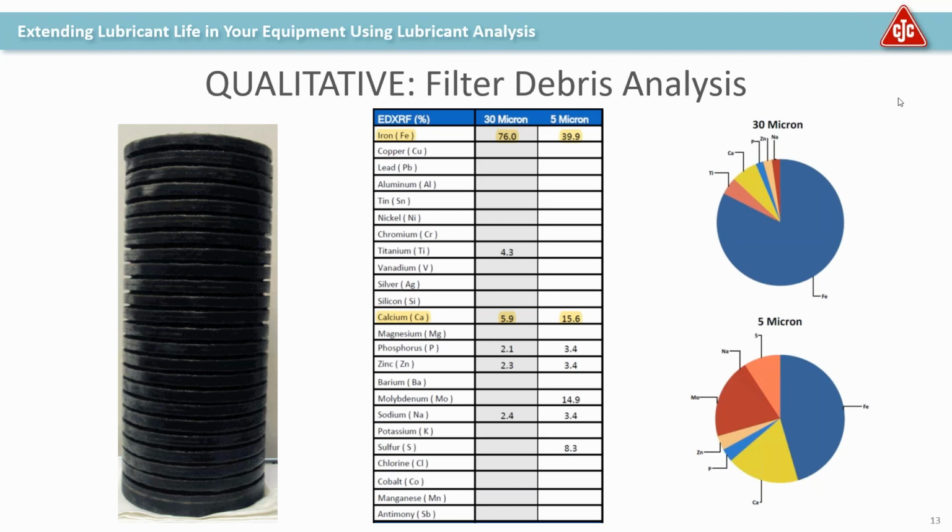So a couple thoughts I have on that is that I think it's dependent upon the application and the system. And anytime you go to re-additize the system, you have to be extremely careful. I know I've seen a number of horror stories where people have used basically splash. They just throw it in the tank and they kind of let it do its own thing. And this legitimately happens to this day. And then it just becomes this kind of gooey mess because the additives are all conglomerated into one another and it forms a sticky gel basically that then coats critical components of the system.